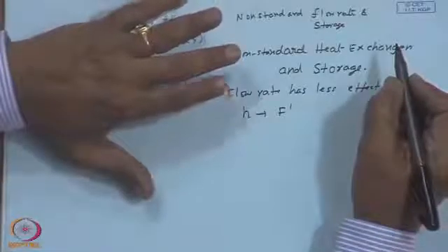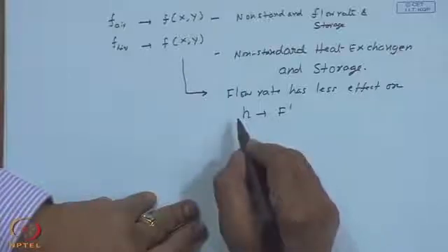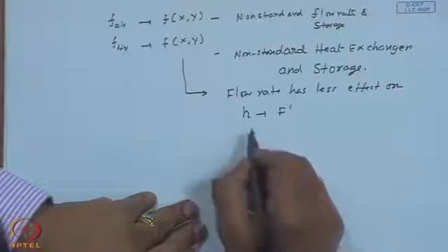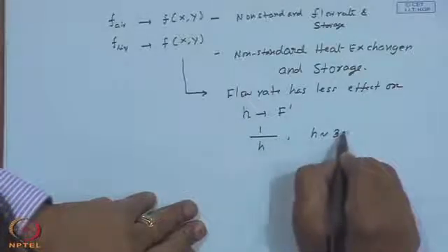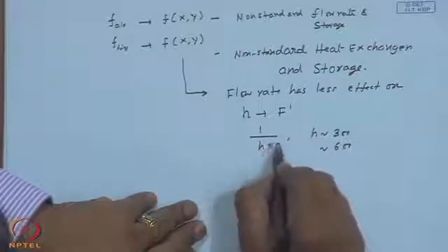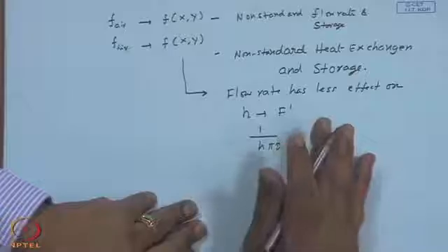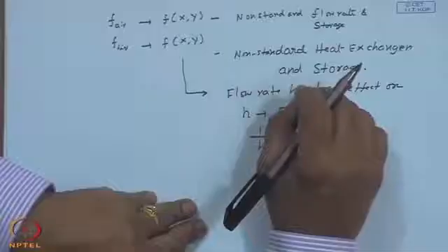So, for flow rate let us say 2 liters to 4 liters, unless the range from laminar to turbulent flow changes, my heat transfer coefficients are pretty much in the same range. And more importantly, if you recall the expression for F dashed, the resistance is something like 1 by h, and h if it is of the order of 300, even if it becomes 600, 1 by h pi d I will be still small. Consequently, the flow rate of the liquid system does not make much difference in F dashed,